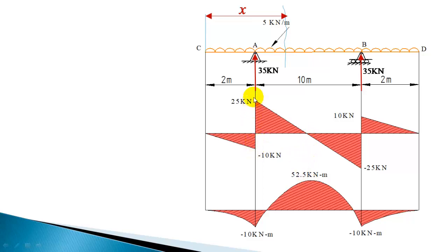Here also shear force is changing its sign, but that point is already a salient point, and you have already calculated the bending moment there. And here again it's changing, and you have already calculated the bending moment there. But under UDL, especially when it changes, you will have slope 0. Here slope is not 0, it is a sudden change, a discontinuity for the load.